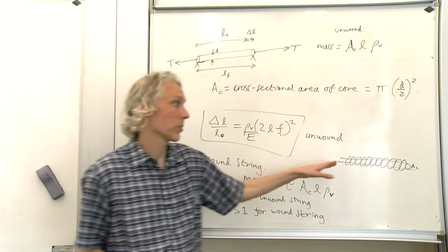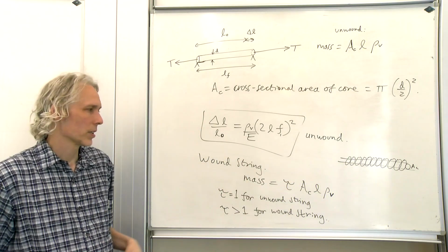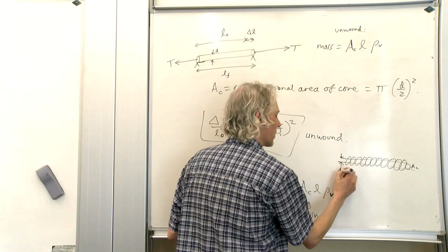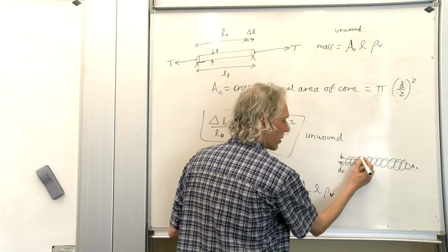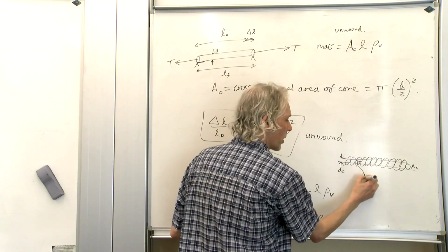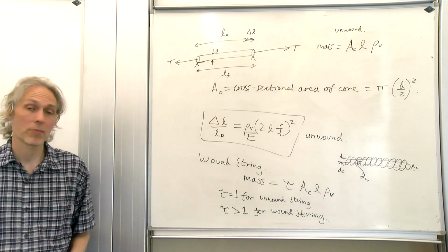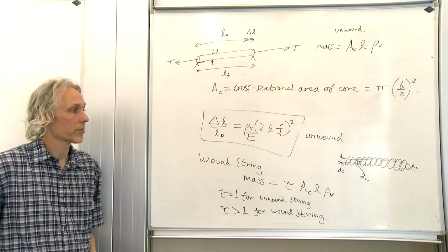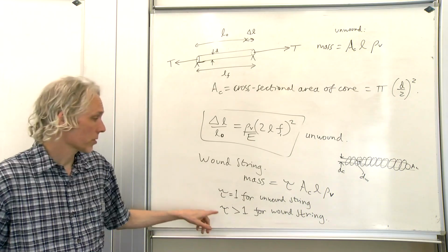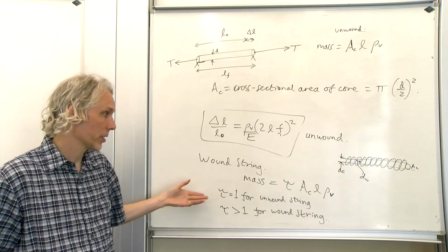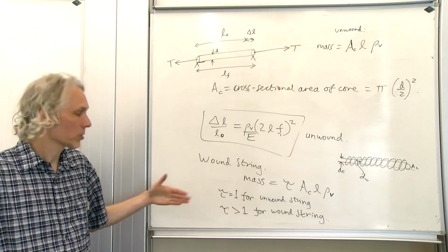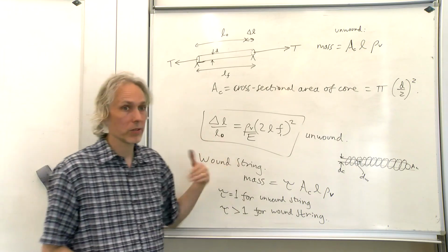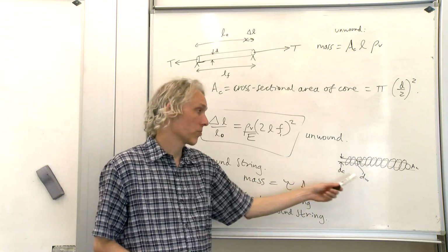Okay, so we can do maths to work out what tau should be for a given diameter of the core and a given diameter of the winding, called d subscript c and d subscript w. Even we could have more than one winding, all that type of stuff. So there is a formula in a publication, or 2 publications, I've done on this type of topic, and I work out what tau is for a given combination of windings and core.